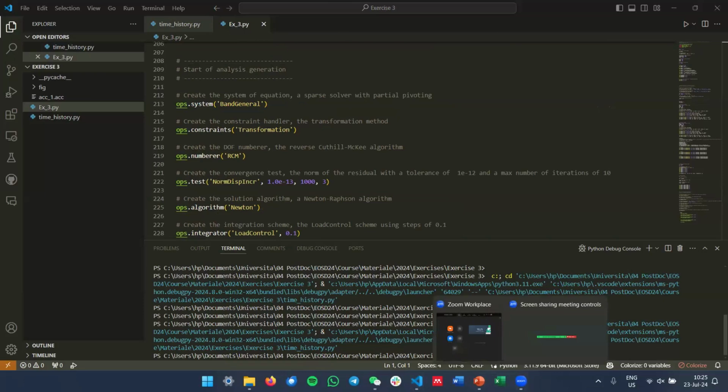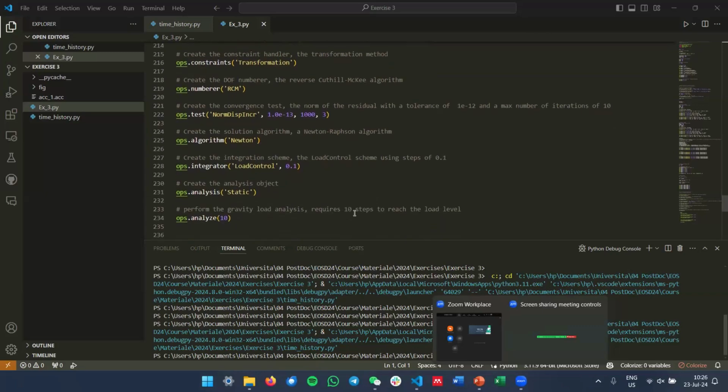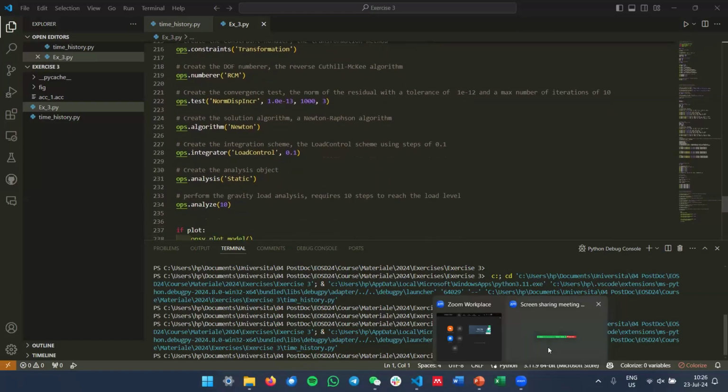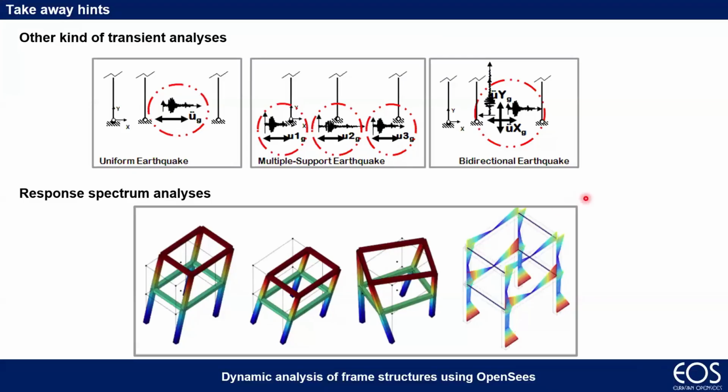It's not working co-rotational with a load. In that case, you just split the loads in nodes, right? Yeah. But I was asking if there's another solution for that. Just split the loads into the nodes of the element. That's the same. Okay, thank you. Of course, all the bending moment diagrams will be different, but from finite element point of view, it's exactly the same problem. Of course, when you plot the diagrams they look strange, but that's another matter. Okay, no problem.